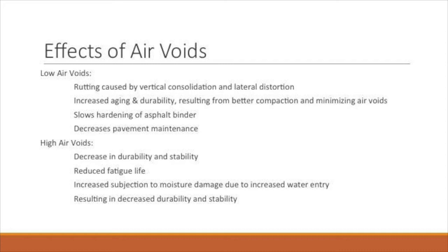High air void content increases the exposure for moisture damage due to the large number of entry points for water. This can cause problems for freezing and cracking. All these things contribute to the decreased durability of asphalt pavement.